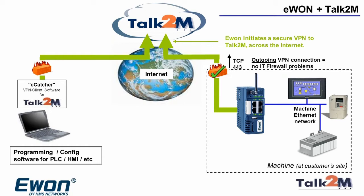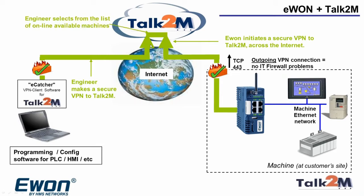That person would sign into the Talk2M account, the same Talk2M account where this Ewon will have been registered to during its configuration phase. When the person signs into the Talk2M, they would see the ends of these VPN tunnels. So they would see these connections coming from the sites, and the person using eCatcher would simply choose to make a connection between their VPN and the site's VPN from the hardware.